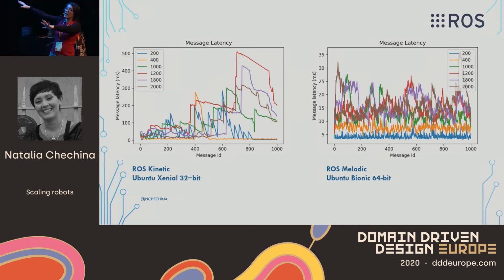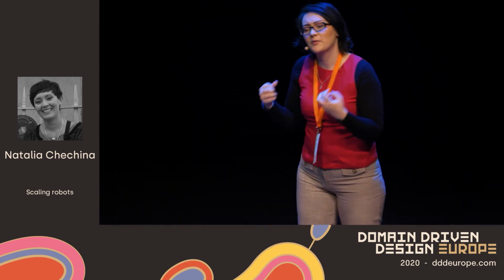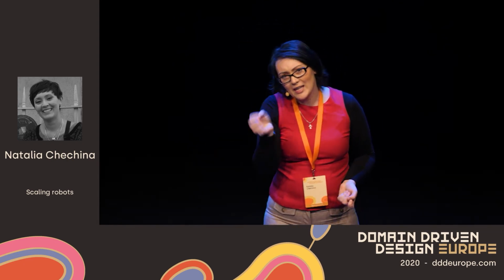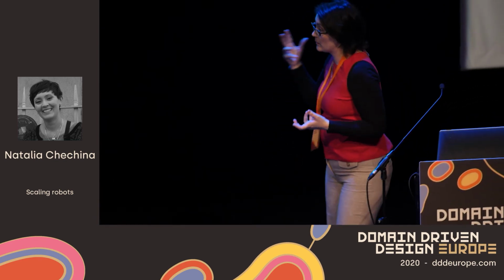So here we have latencies in milliseconds, the lower the better, and message ID, showing how long it took each message to get delivered at different frequencies, shown in different colors. If you can see there, for ROS Kinetic it goes up to 500 milliseconds, whereas for ROS Melodic it goes only up to some 35 milliseconds. So the difference is dramatic, right? The advice and lesson that we learned is to pick the key characteristics that you really care about, run some simple benchmarks to see how different operating systems and different middleware perform, and then go for the one that works better for your particular case.